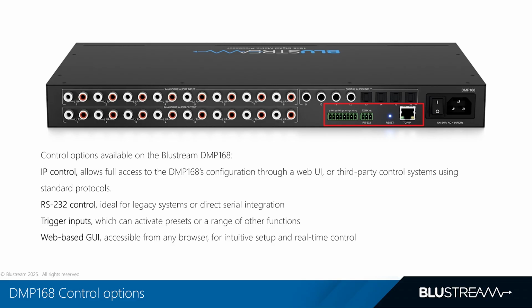So the DMP168 gives you several ways to take command, whether you're setting it up, automating it, or handing control over to a third-party system. We've got IP control, and this means you can connect the unit to your network and access it from any device with a browser. The built-in web UI lets you configure settings in real time. Plus, it supports industry standard protocols, so it can easily integrate with control systems like Crestron or Control4.